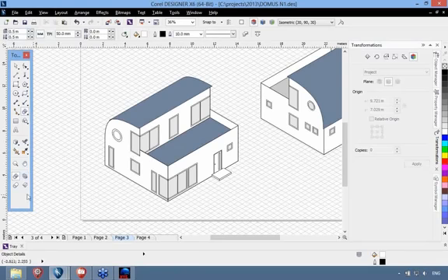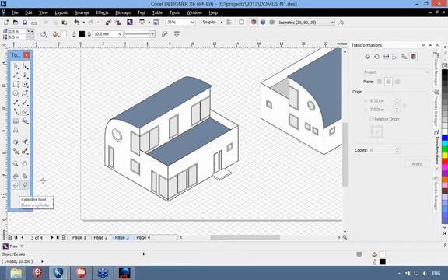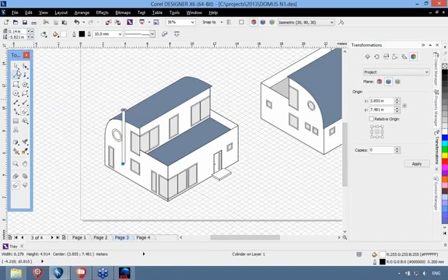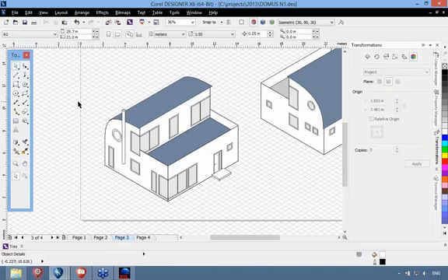In this architectural sample, it's not really about threads or wells. What I want to do here is using the prism tool, and I can do that in the projection plane that I had selected. So it draws a circle, and then in the next step I set the height. I do all that interactively. As you can see at the top, I can also use parameters, coordinates for doing that. And there you go. Done in one step. You have created that object in addition.